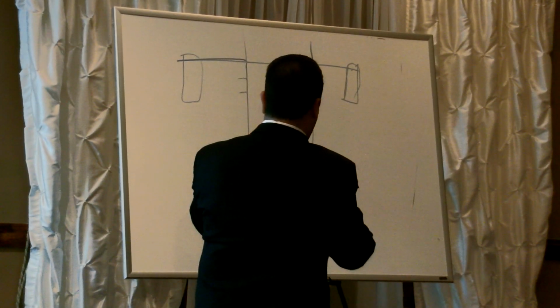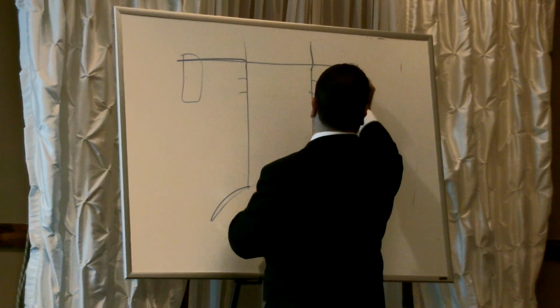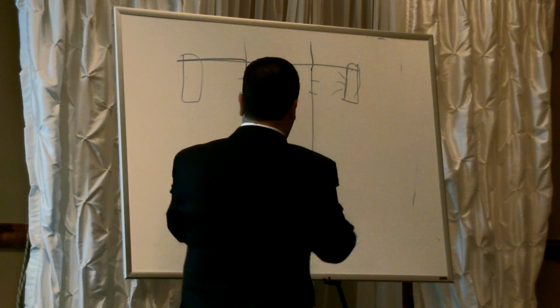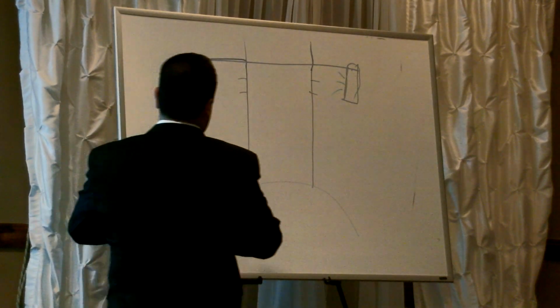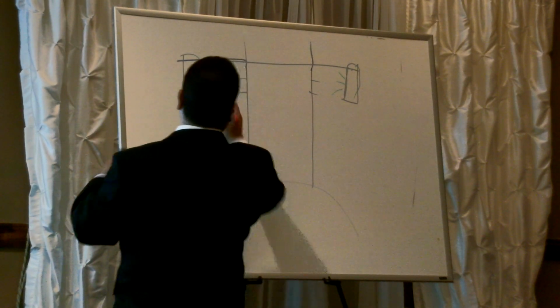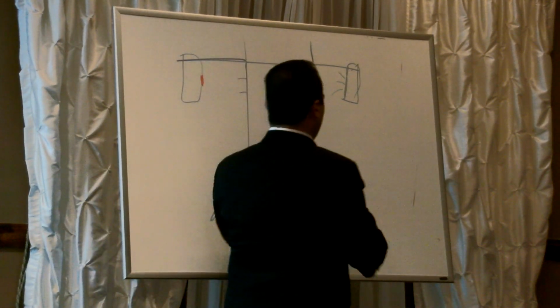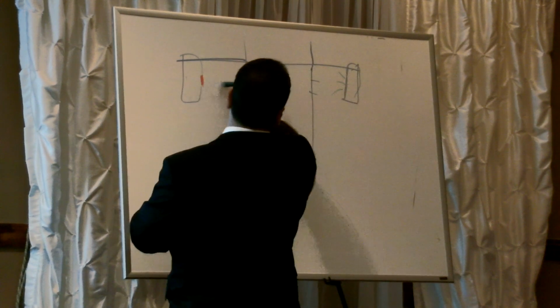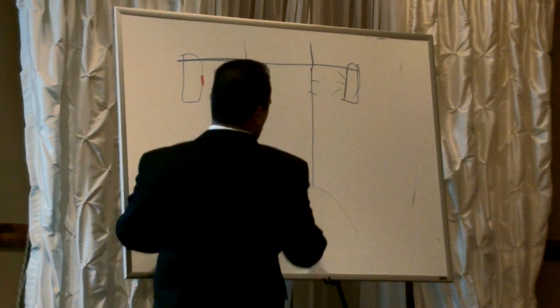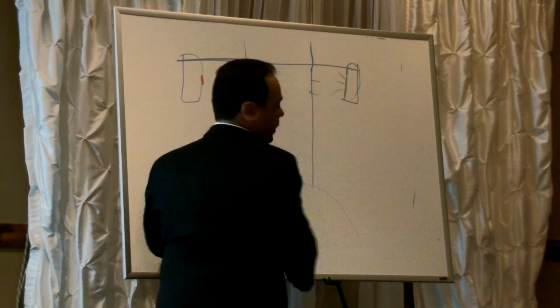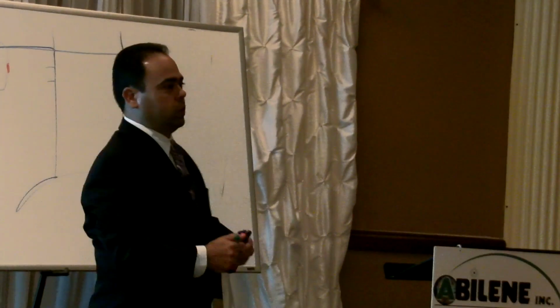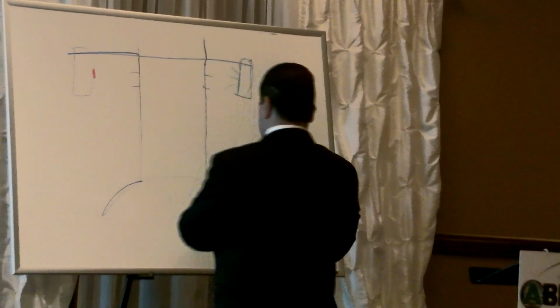One is a light. This is the receiver. What it does is it shoots the light through this breaching, right? And if the smoke breaks the beam of light, it tells somebody that the burner's smoking and shuts the boiler off. It's a requirement, right?